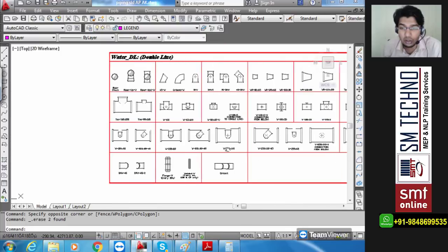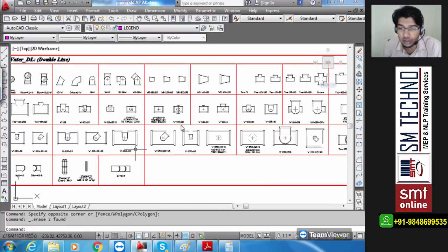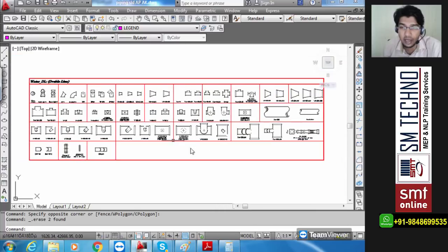All right. So this is all about different categories of the catalog pieces that you have, and this will be generated and created only and only on scale of 100. It will be provided to you by the manufacturer whose manufacturing fittings you are going to use. You should never try to move any of these catalog pieces. You cannot use the M enter command and move them for using inside your drawing.